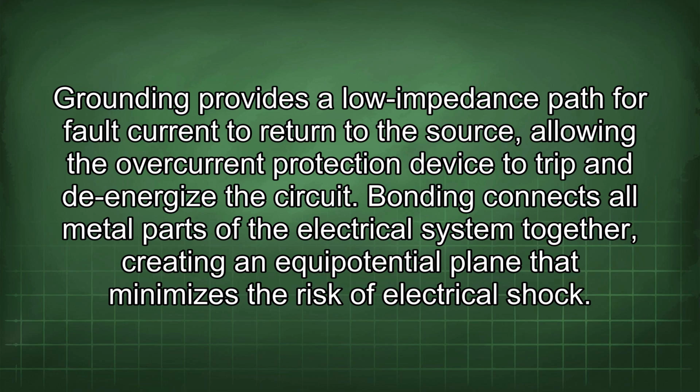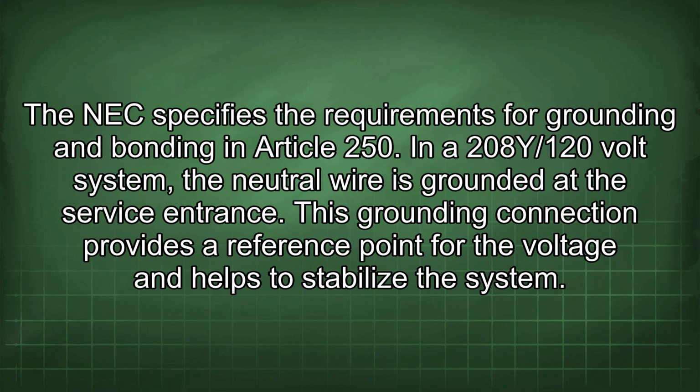Bonding connects all metal parts of the electrical system together, creating an equipotential plane that minimizes the risk of electrical shock. The NEC specifies the requirements for grounding and bonding in Article 250.